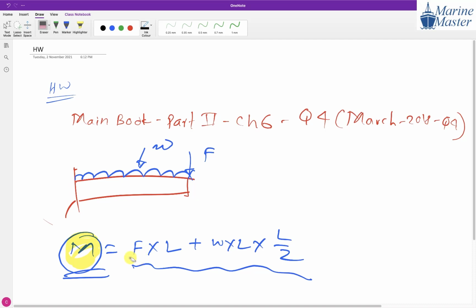Remember, bending moment is a summation of moments. Don't consider here only a simple moment. If I am writing capital M in the bending equation or this discussion, though I am saying moment, it is not a moment, guys. This is the bending moment. And here, don't worry about sagging and hogging. What you have to worry about is how to calculate the bending moment here. Clockwise, anti-clockwise, that you have to consider. Then things will become simple.